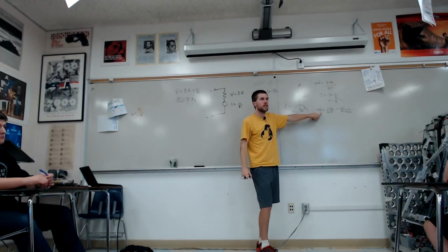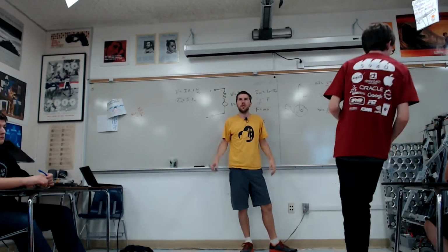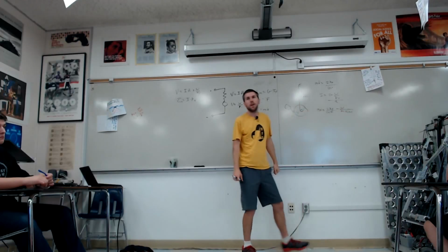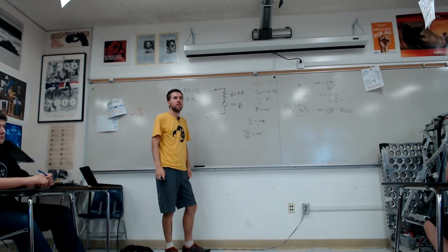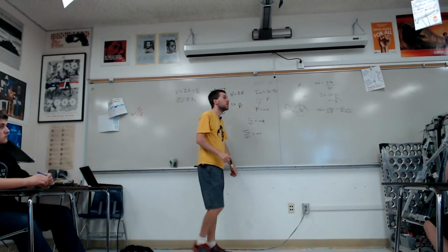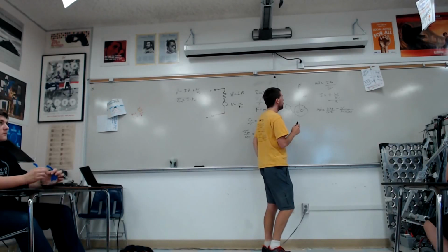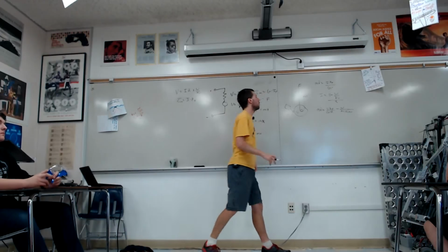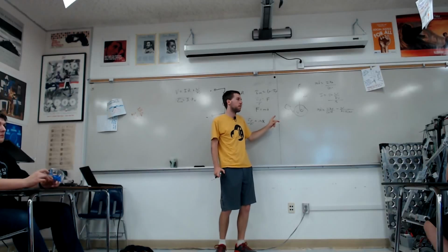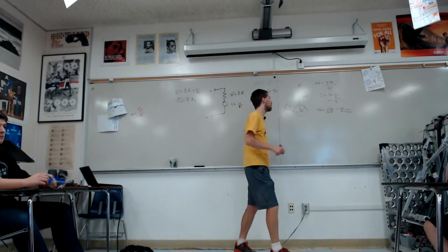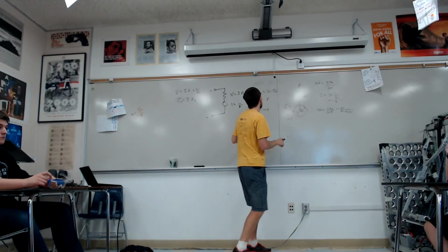So the acceleration is related to the angular velocity of the motor. Those aren't very useful units, so we'd like to get rid of the angular velocity of the motor. We've got to convert the speed of our motor to the speed of our car. So you want to use the gear reduction. Yep. Whereas our gear reduction made our output torque higher, it's going to make our speed slower. So it's the inverse of the gear ratio. So the angular velocity of our motor. Let me make sure I get the sign right.